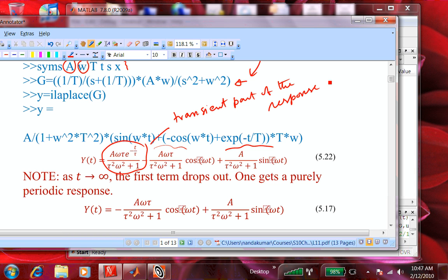But in the impulse response, what happens? The original steady state is recovered. You're perturbing the system, the original steady state is recovered in impulse response. Step response, you go to a new steady state. In a sinusoidal forcing, there is no steady state because the response continuously oscillates with time. What is the frequency of the oscillation? It turns out that it is the same as the forcing frequency. For all linear systems, that is in fact true.